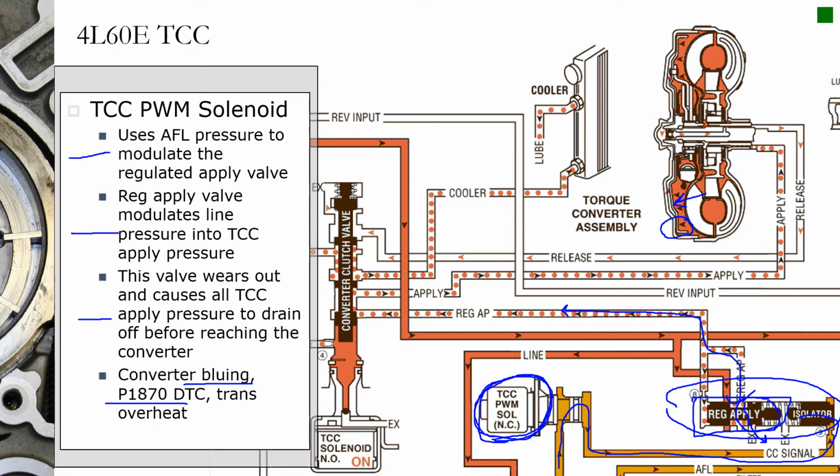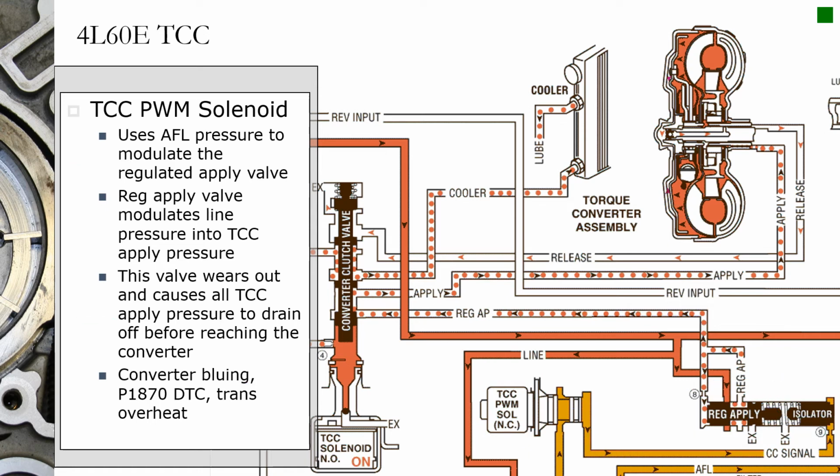Superior. There's a few different companies that have ways of fixing this. Even General Motors, when they rebuild it, you get a remand from them. They bore out the case and put a bigger valve in there. But the problem is that the casting is what's soft and wears out. So just boring out the existing valve body and putting a bigger valve in there, you're still going to wear that one out. So really the best option is to use like the Sonex valve, where you bore it out and you end up putting in a new bushing in place of the metal that you bored out, and then a valve in there, so that the new valve is working on this fresh aluminum that's a higher grade and doesn't wear out as quickly.